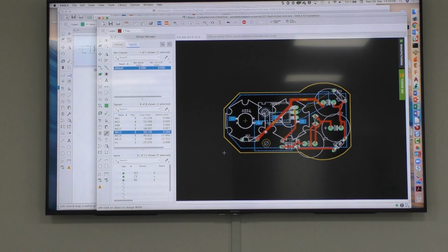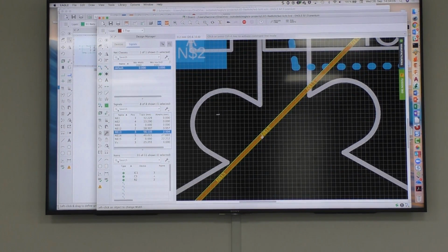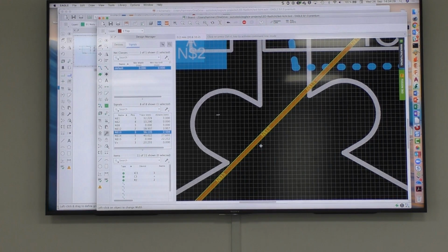Now I should do a control right click. Yes, no, yes. Yeah. It's small now. You only see that's the DRC error point. But that's possible now. So that's a far easier way of doing it. We do not need all the ULPs. All the ULPs were written because somebody needed this functionality. Now we don't have it, so we make a ULP for this. Meanwhile, we have some of the functionality directly available, as we have seen here with the design manager.